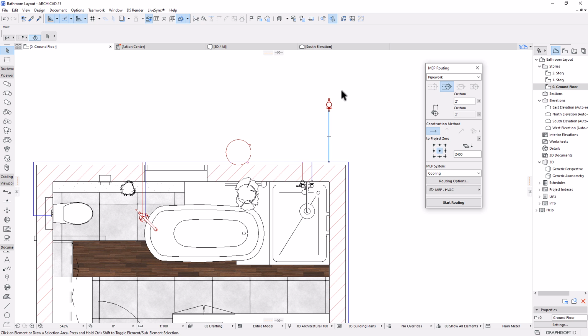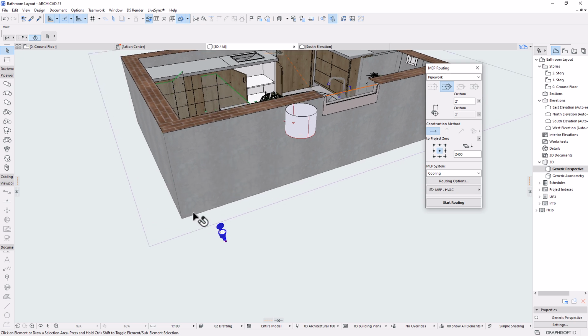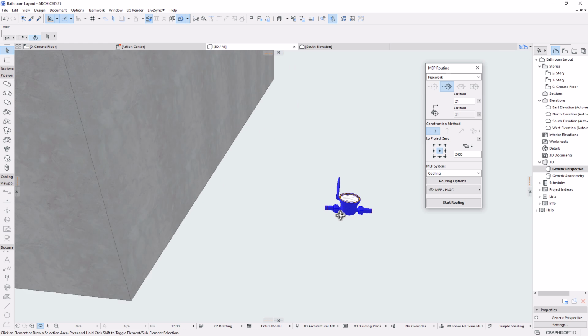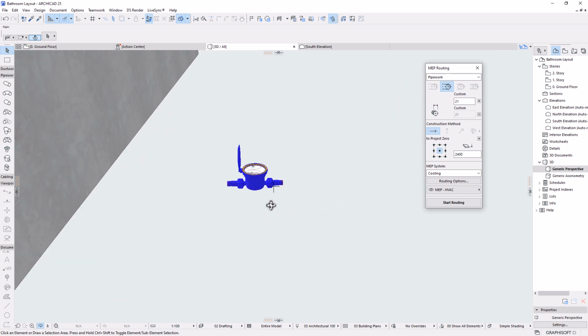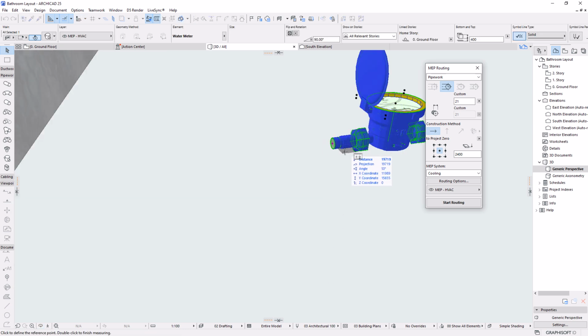The most important thing is to understand, in 3D, what is coming from where. We need to understand the heights of the components you are connecting to or routing into. So for example, if you measure the height of this element, let's select it. I'll hit M on your keyboard to activate the measure tool.